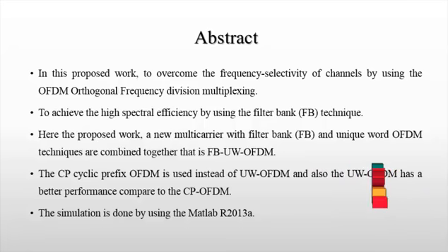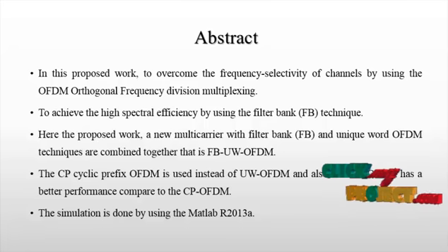The MIMO concept: the multiple antennas in a MIMO system can be exploited in two different ways. One is the creation of a highly effective antenna diversity system, and the other is the use of multiple antennas for the transmission of several parallel data streams to increase the capacity of the system. Antenna diversity is used in wireless systems to combat the effects of fading if multiple independent copies of the same signal are available. They are combined into a total signal of high quality, even if some copies exhibit low quality.